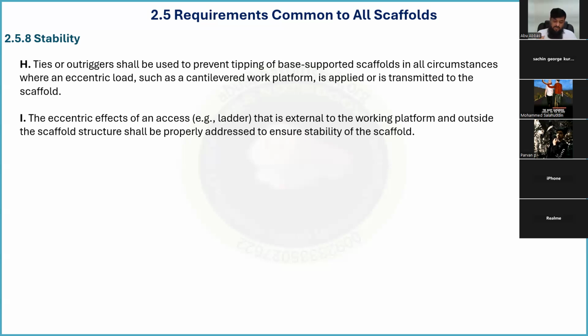For towers, an internal ladder is preferred because when the ladder is internal, the load remains inside the posts. It does not become eccentric or critical. When the ladder is outside, as the person goes up, there will be a load factor, what is referred to here as eccentric load, as an additional load at the time of movement.